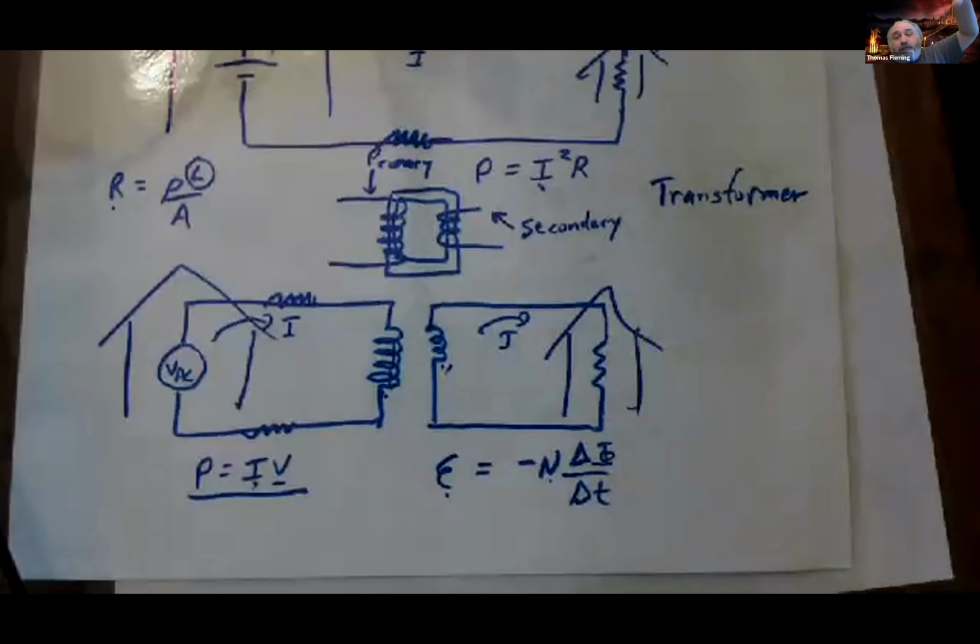Then that substation might go to a neighborhood substation. And you see those around, they're usually fenced off. That neighborhood substation might go from 10,000 volts down to a few hundred volts. And then that goes out to your individual neighborhood. And if you look at the top of light poles inside your neighborhood, you'll often see these little round, often green objects. Those are transformers. And inside those transformers, what it typically does is step down a few hundred volts to 120 volts. That 120 volts goes directly to your house. And that's why your house is powered at 120.